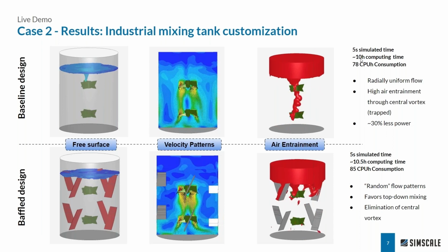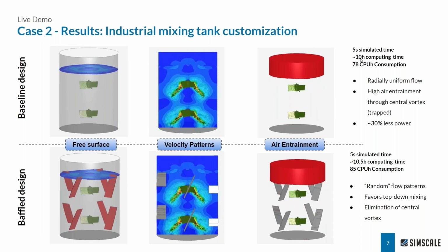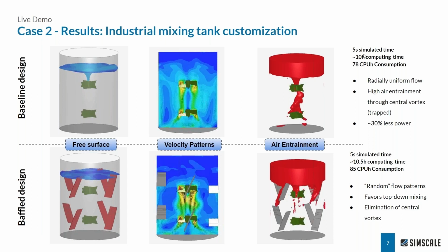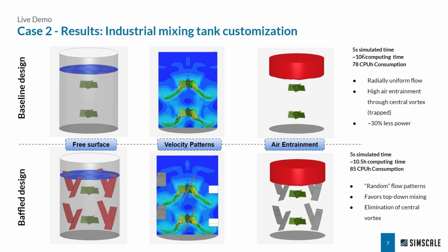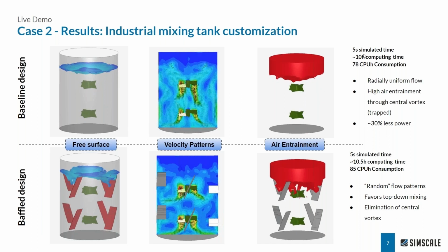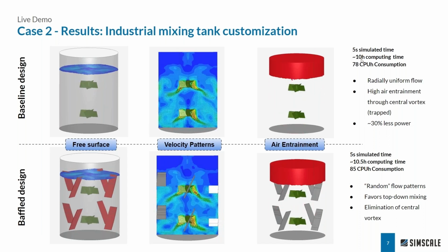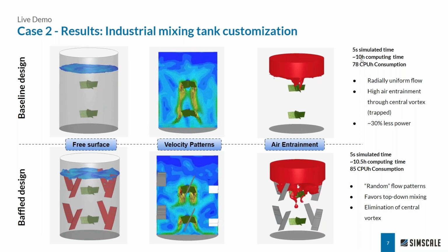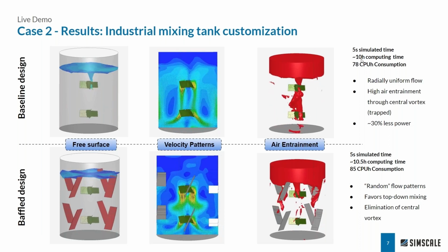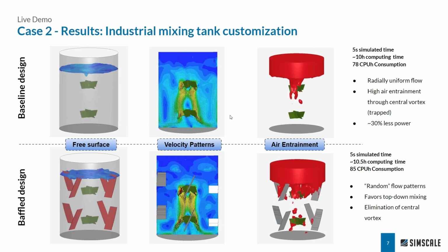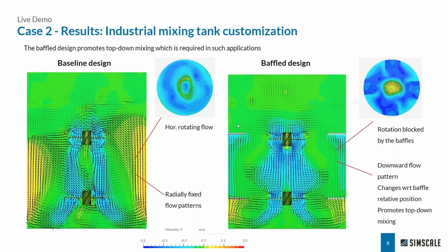While for the first example, it took us only 2 hours to simulate this filling channel. Here, we need a bit more time. It's 10 hours, mainly because we have this rotating motion, and we need to have a very fine mesh next to the blades so that we capture the behavior more precisely. So that one took more time, but that's not a problem. We can run 10, 20, 50 designs in parallel without issue, and all of them will complete in 10 hours approximately.